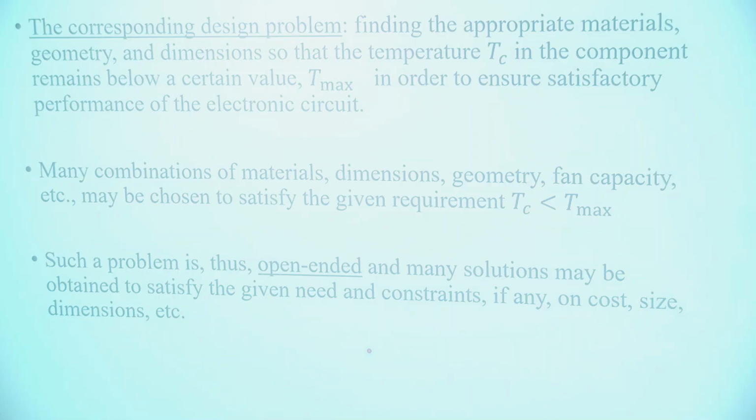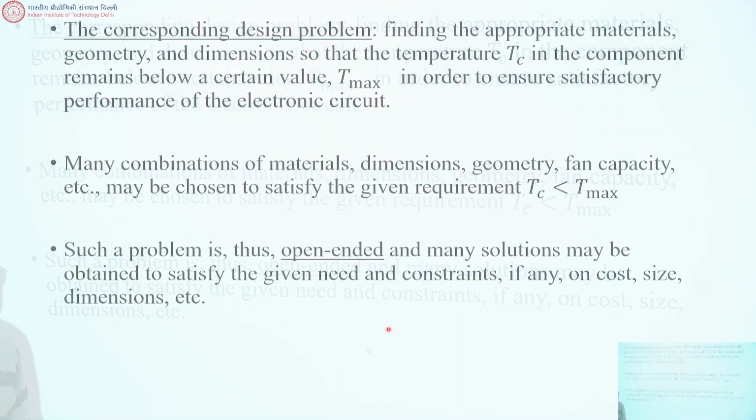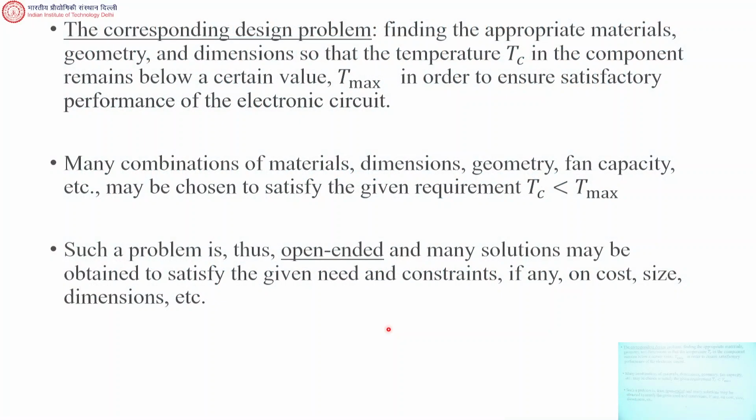So in a heat pipe, what happens is that phase change is used. There's some liquid in the heat pipe, and the liquid picks up heat from the hot component, and then it evaporates, then it goes somewhere else, and there it condenses, thereby releasing that heat.